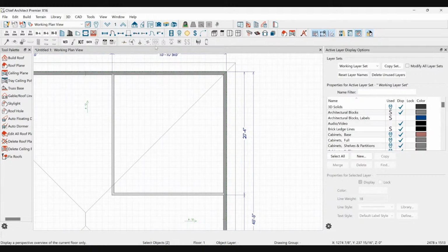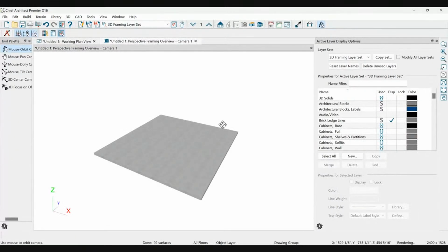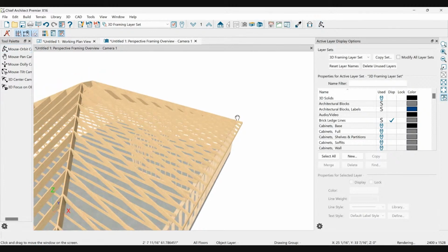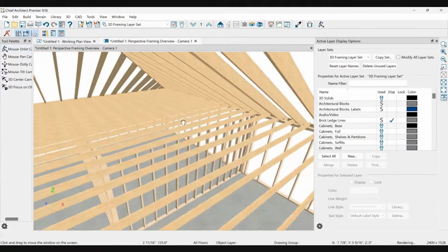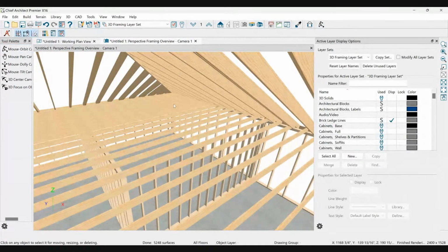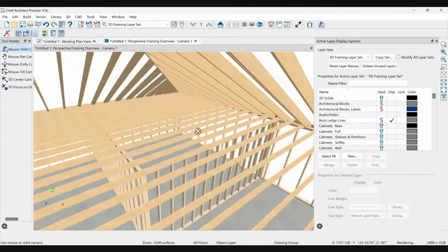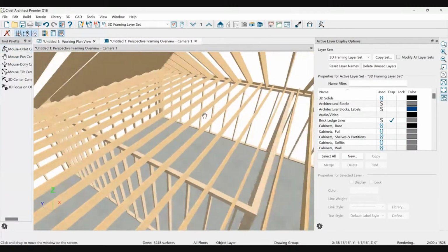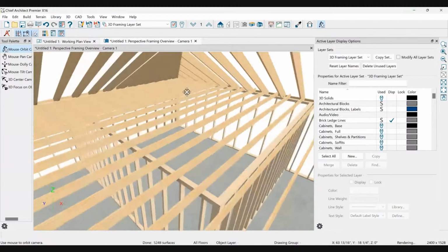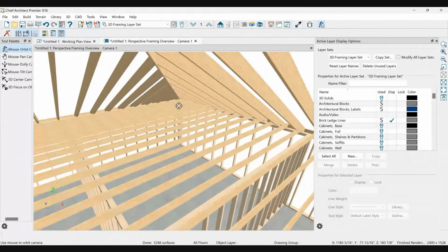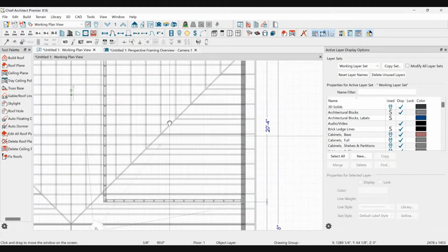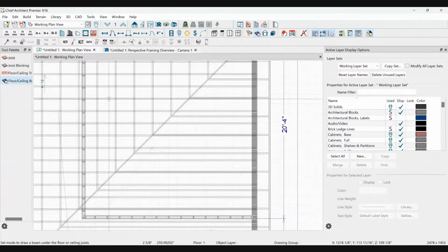which is here. I don't normally use the framing view. Oh, geez. This is why I change all the settings in my templates. Okay, take a look at what we've got. All right, this is fine. We are inside the attic looking down at the master bedroom. This hip over the master bedroom has to basically cross the master bedroom. As it is right now, I could very easily take a beam and run it across the master bedroom like this.